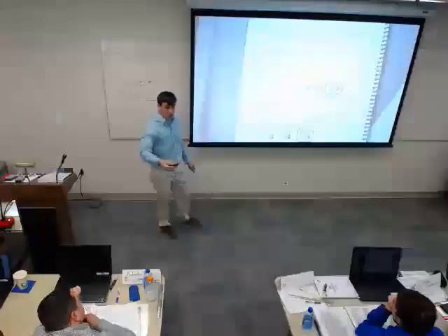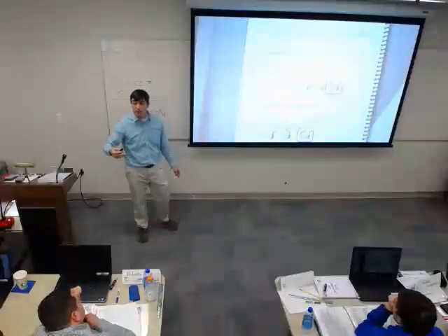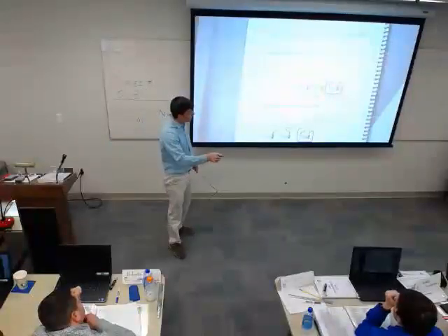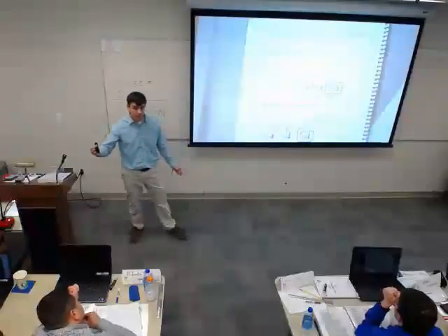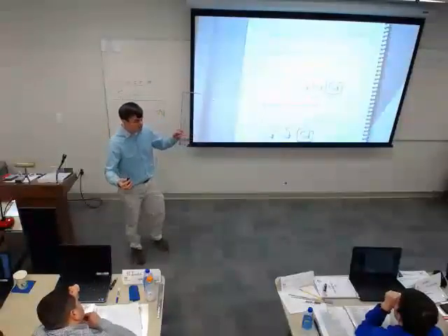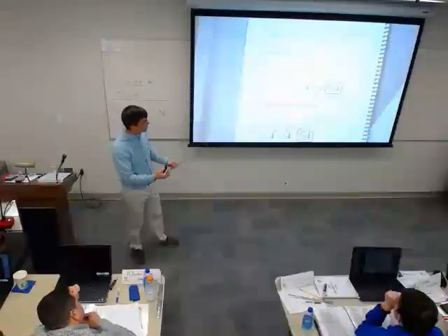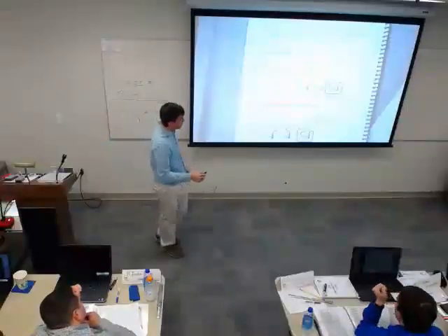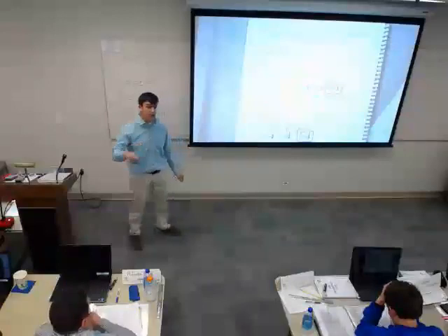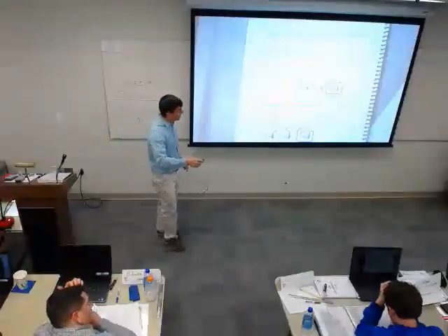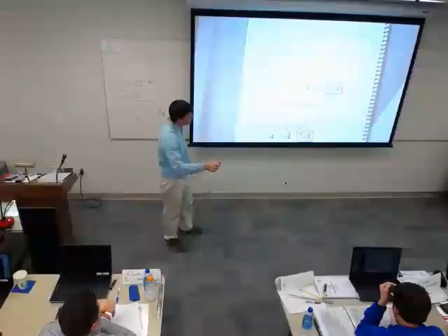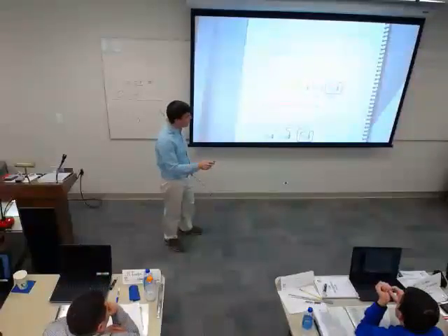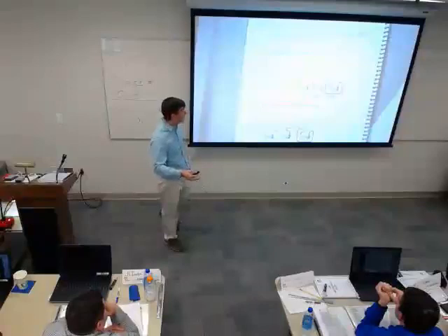But if I want to know my velocity pressure, which is what I want to know to determine my velocity, I can hook both of them up. So I hook up which number is going to be smaller? Which one do I hook up to the low side? Static is going to be a smaller number, because total is static plus velocity pressure. I'm going to hook up the static to the lower side. I'm going to hook up the total to the positive side, and now I'm going to see the difference in those two. So now I've got my velocity pressure.